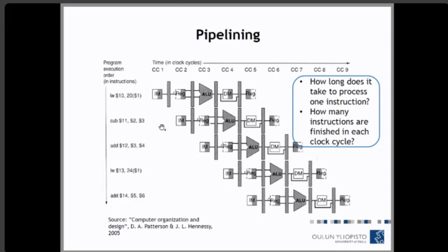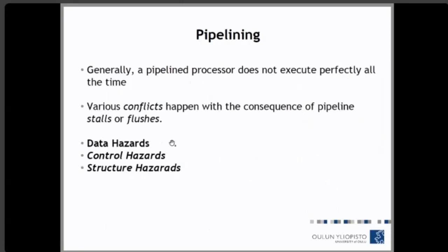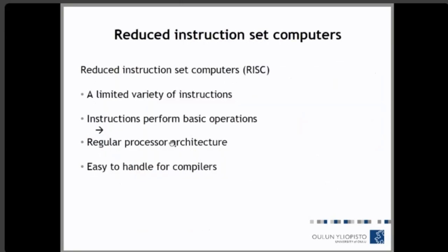So they use the same arithmetic unit. And let's say it really can't be finished in one clock cycle. So while the sub is in this ALU, add will arrive and ask to get into the ALU, but can't, because that part of the ALU that does the addition operation is already occupied by sub. So here we will have a structural hazard, and the pipeline has to stop.